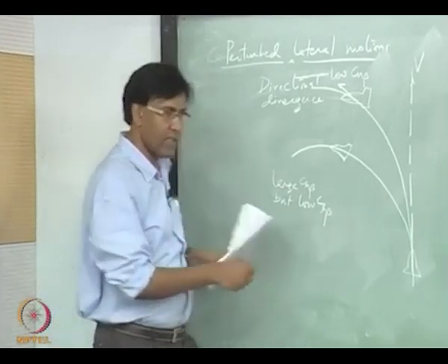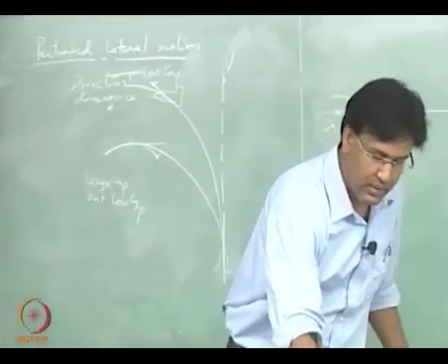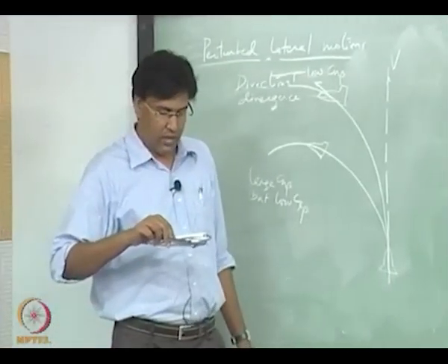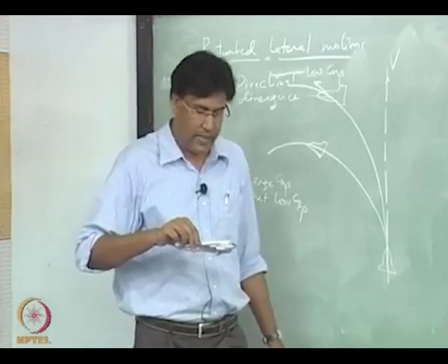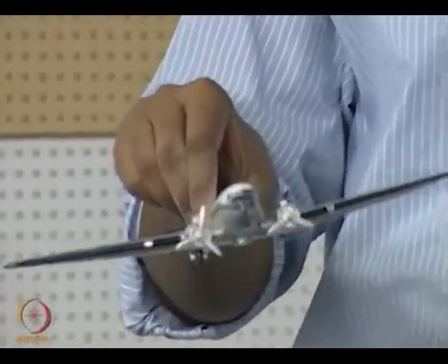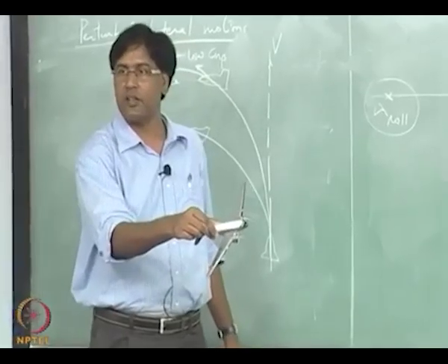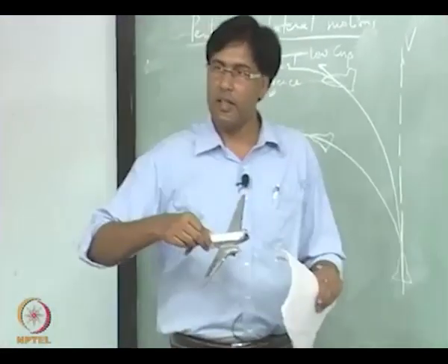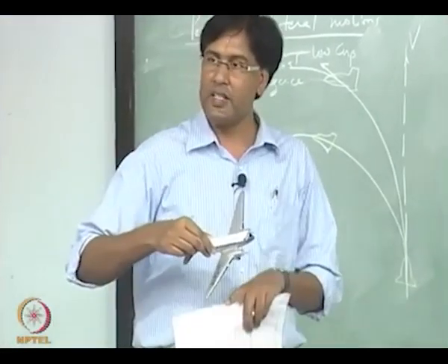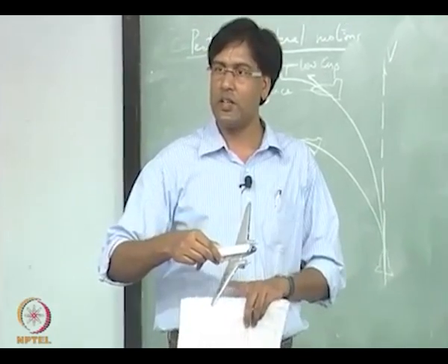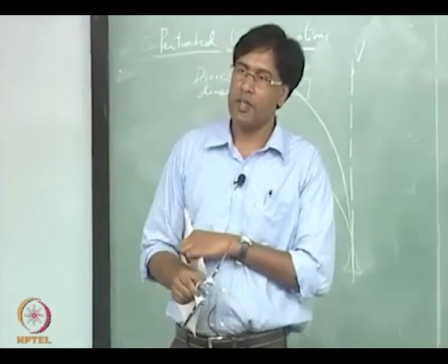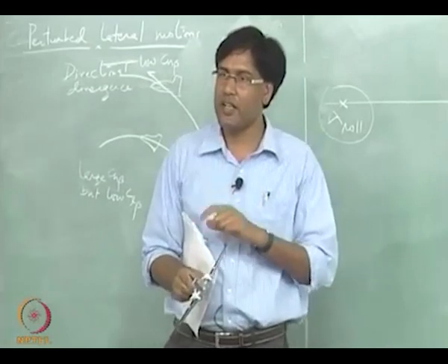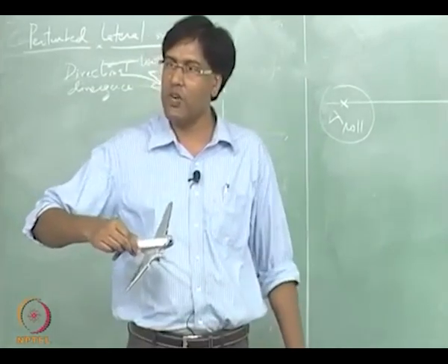So slowly the aircraft is killing the beta, moving like this, but it is also turning. Because the bank is introduced now, you will have a lift component which will be lower than the weight, so it will also start going down.